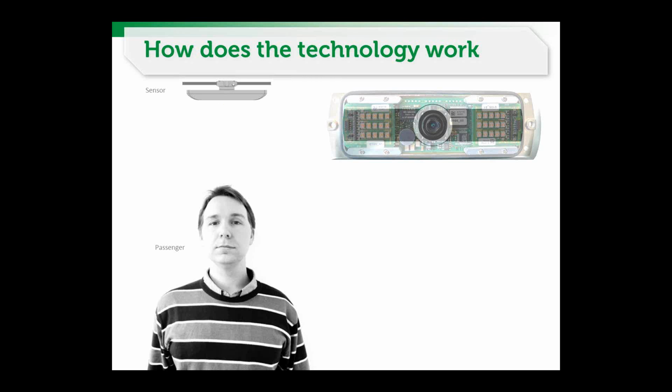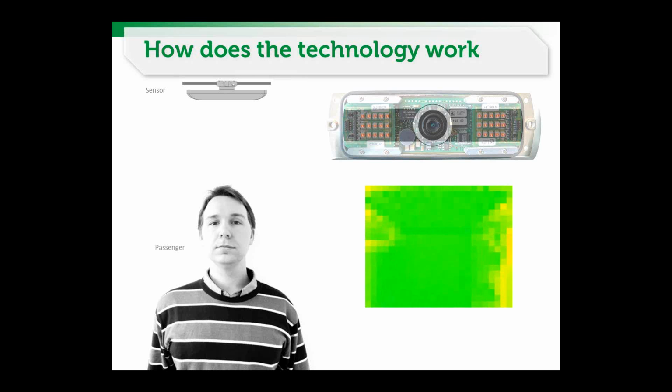They're sending out the door area, the beams, and the reflection goes then back to the sensor. In the middle, you see a CCD chip, 500 pixel, and this is taking the information, and out of that will create a picture. So, as you can see, the animation below. So you see people walking in, and the red is...